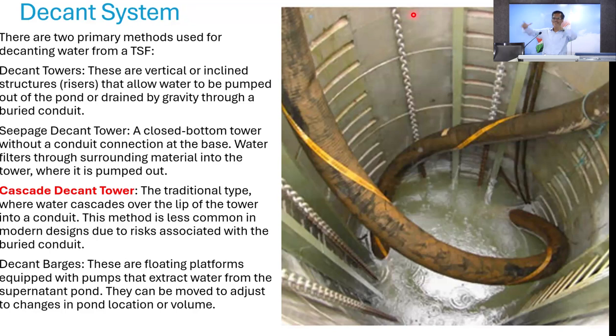I have put a vertical well there. When I stop the water, the water automatically rises in the surge shaft. That's called a surge shaft. It will just rise above the hilly terrain. That should be again within a container, the water should not come out of it. So we put a container, and it rises around 10 meters, 12 meters, 20 meters, depending upon the height. So there it is against the gravity, and here it is just opposite.